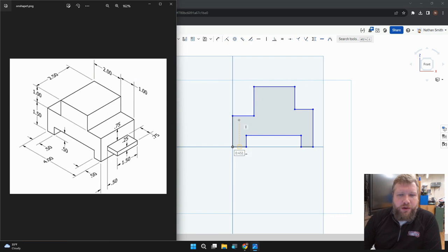All right. So before I go and start adding dimensions, I'm going to just kind of look at my part first. And I noticed that there are some relationships between these things. So not just those horizontal, vertical, and perpendiculars that were dropped in there, but I also have these two little legs are 0.5. Therefore, they are equal. Okay. I also have a 1-inch measurement here, a 1-inch measurement there that I could use if I wanted to. I see a line, this extension line that comes from this corner to show me that this is 1 inch tall, goes through this line as well. So I know those two features are lined up with each other, which on mine, I did not do.